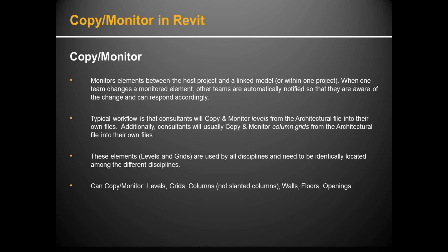The Copy Monitor tool monitors elements between the host project, which is typically the architect's Revit model, and a linked model, or it can be done within your own project. We don't use that tool that way very often. The benefit is that when one team changes a monitored element, such as a level or a grid, other teams are automatically notified so that they are aware of the change and can respond accordingly.